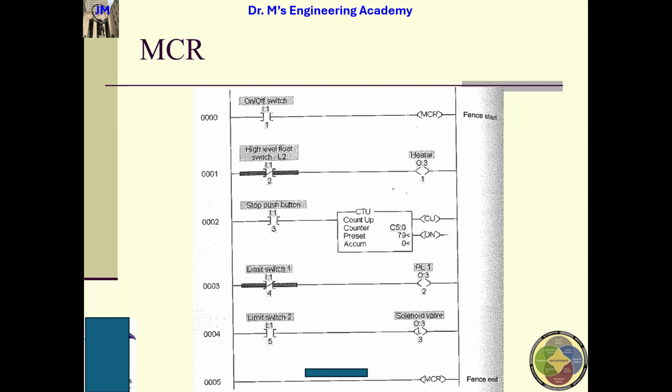And for the start button, if you do not click it, it just looks normal. If you click it, you can see it immediately turns bold green. Pay attention next time. Okay, so here that means this guy is true at this instant. So this heater is non-retentive. Why? Because it's a normal output. You understand, guys? It means that if this guy is true, this is turned on. If this guy is false, this guy will be turned off immediately. Okay.